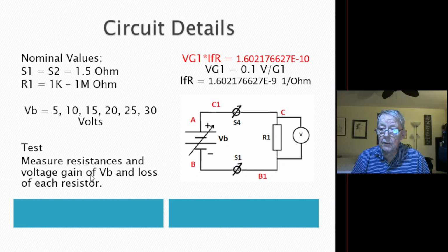And when I go to do the test, I have to measure all three resistances using 4-wire measurement, and then measure the voltage across each one, and then I can calculate the current. Remember, current is not real, it's a calculation. So those are the circuit details I used in the